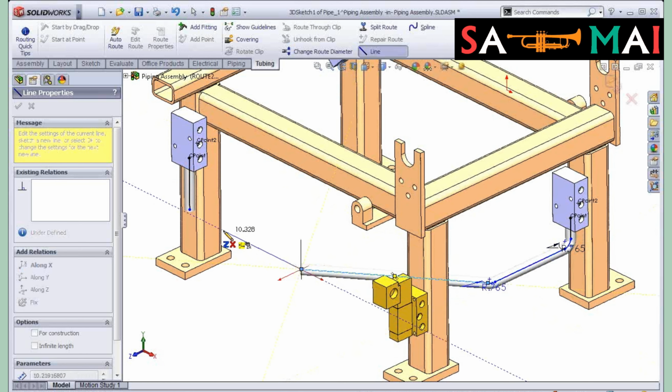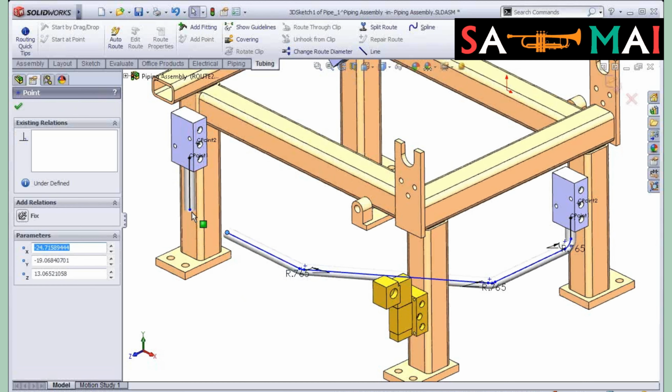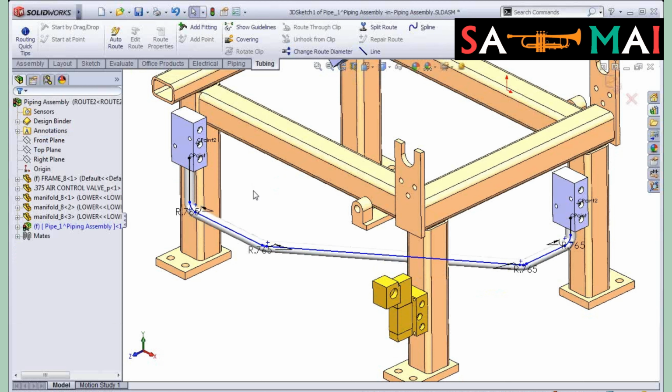And then I'm going to come over here and just get close to where I want to be, somewhat in the right direction, not actually try to touch the end point where I want to exactly go to. Then I'll take those 2 points and do a merge relation between them. And that connects them together. Then it doesn't go over to find on me or flip weird on me or anything like that.